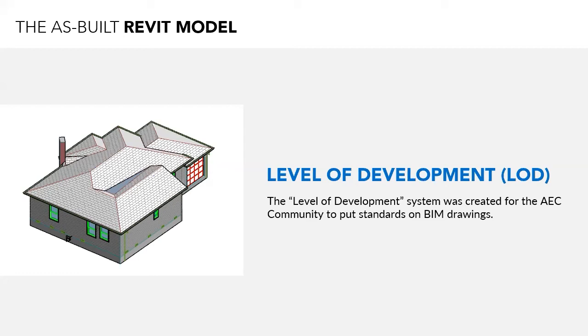Level 500 on the most complex end is so thorough that the model of the building is essentially a virtual version of the entire structure: nuts, bolts, bolt threads, bolt diameters, bolt lengths, washers, and all. So when modeling as-built plans, somewhere between LOD 200 and 300 are the most practical levels for a light and usable Revit model. So even though laser scanners gather a ton of data out in the field, you're still assessing